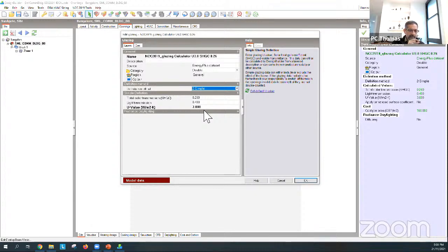Even though it says the definition is simple, it's not a really simple model. It's quite complex under the hood. EnergyPlus has a really complicated model where it looks every hour at the technology that fits within these 3 design parameters, and it works out an incident angle modifier curve.